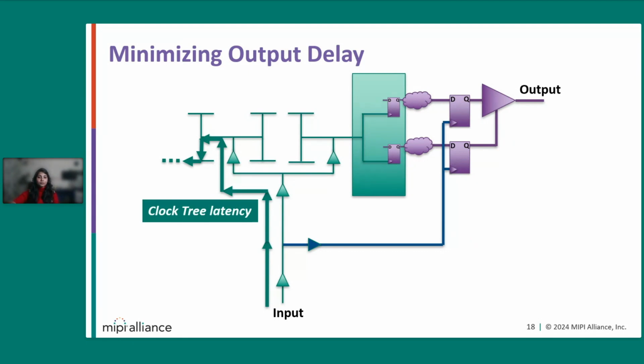For that, we can have a separate branch from there, and in blue we can see a separate clock tree for the output register that will not be part of your main clock tree. And this is because the bypassed destination register's clock can reach much faster than the source register clock.